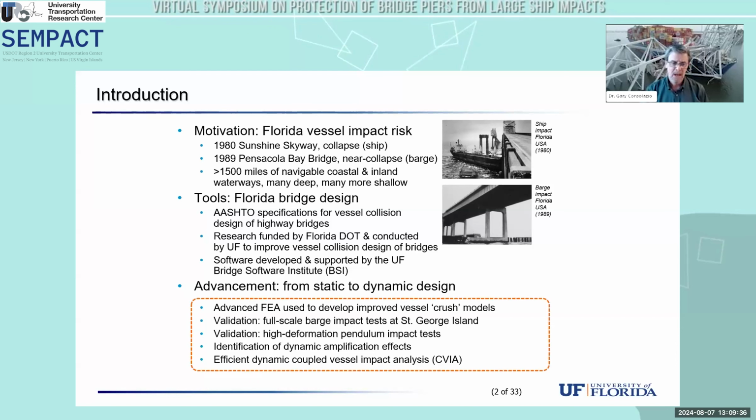Now, I mentioned I'm going to be talking about how we advance from equivalent static approaches for design to efficient dynamic approaches. And some of the things I'll be touching on as I go through the presentation are outlined here. That is the use of advanced finite element simulation to develop improved, I'll call them crush models, basically force-deformation models for vessels, validation at different scales, both full scale and reduced scale. Importantly, the identification of dynamic amplification effects. I'll talk about that a bit. And then equally importantly, how do we efficiently capture those amplification effects using efficient dynamic analysis?